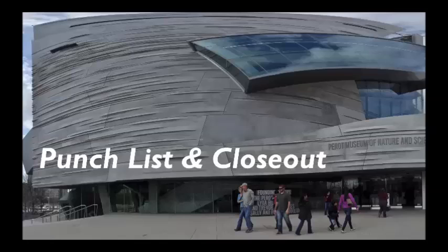And the very last thing is the punch list and closeout. So usually the contractor, before occupancy can take place, and this may even be before the city or whoever is the inspecting authority issues the certificate of occupancy, usually there's some closeout procedures where they need to have a checklist of all of the things that need to be in place before they can hand it over to the owner. Sometimes it's involved in their scope of work and the architect's scope of work. They go through the last several steps that need to happen before they can consider it to be done.